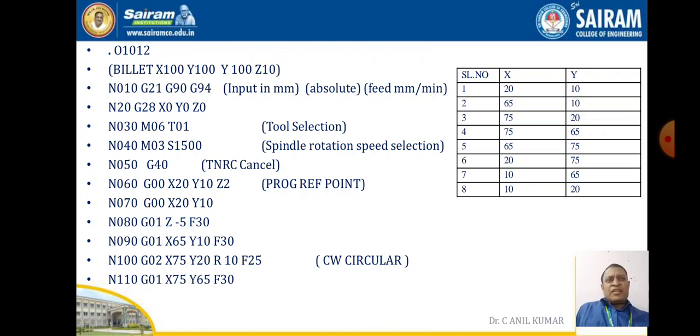After the fillet radius, the X dimension is 10 and the Y dimension is 65. If it comes down, the corner point slightly above the starting point has X dimension 10 and Y dimension 20. Once we locate and identify these points, the programming will be very easy.